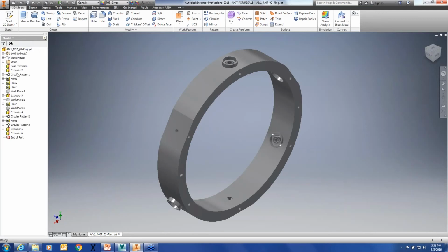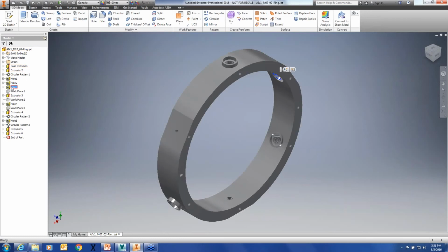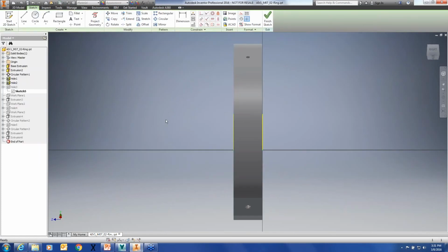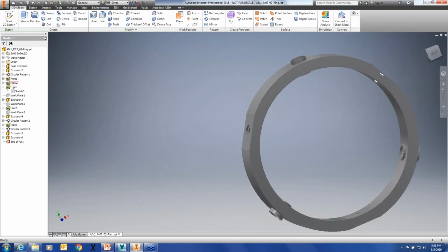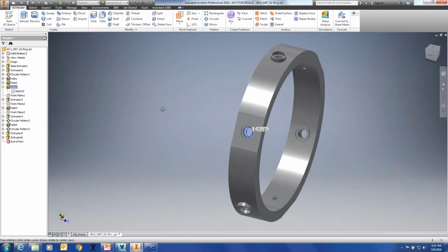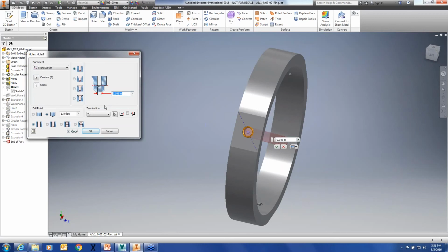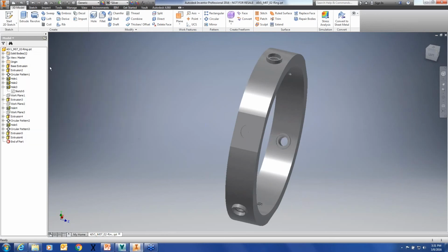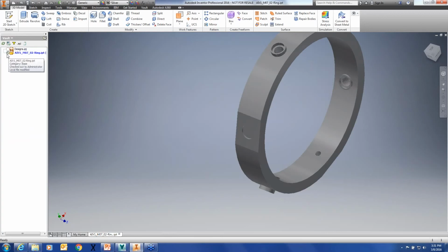Another nice advantage here is, if you are currently Inventor users, obviously you're using the model browser a lot to make your changes. Let's say we'll just make a change to a hole here. Go edit the sketch. Oh, on the wrong side of the sketch here. That wasn't the right one. Let's close that. There's the hole itself. Let's edit feature on that. Change the hole to maybe 0.5. And we'll save that. Now if I look at my Vault browser, it turns green, saying that our local version is newer than what's out in Vault.